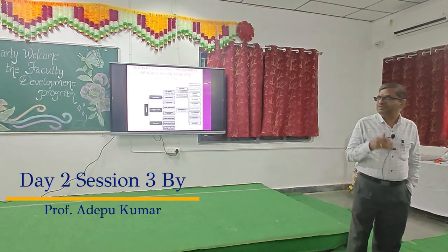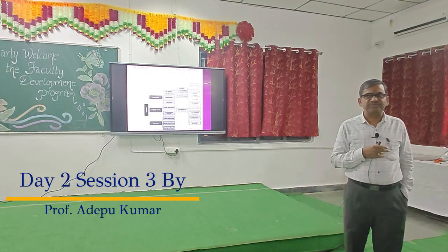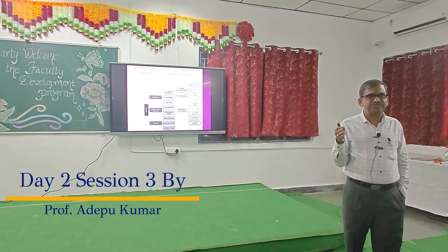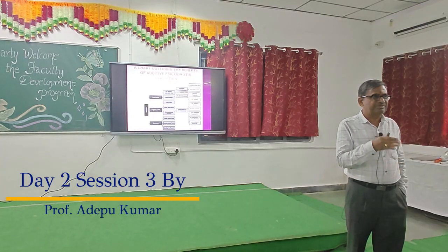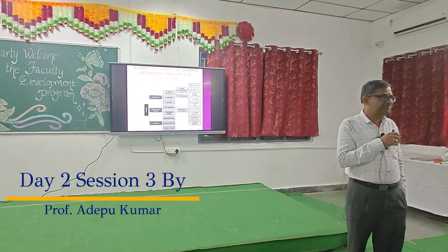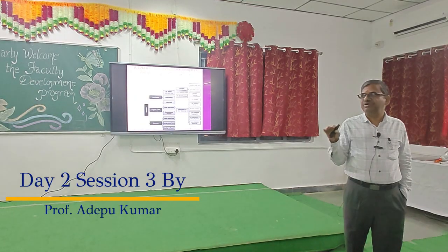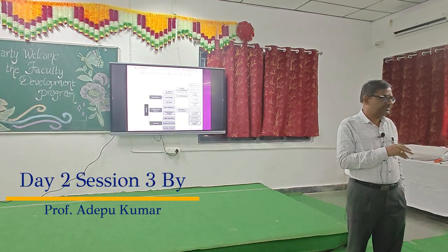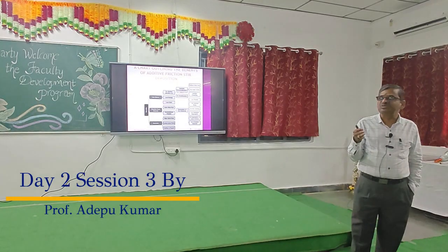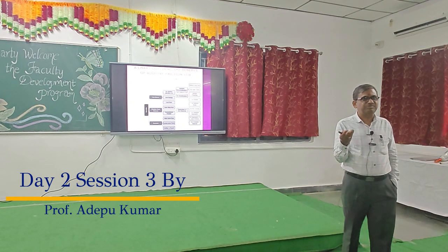For example, aluminum alloy 2024 does not respond to heat treatment process. Once the material does not respond to heat treatment, after building the additive manufacturing component, the component properties are inferior to the existing material. Then you need to compromise the properties of the material when you go for additive manufacturing. Suppose it is a complex geometry and there is no other way to build the component using the same material, then you need to compromise.